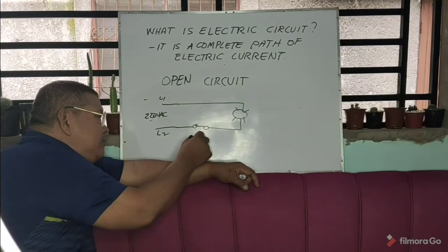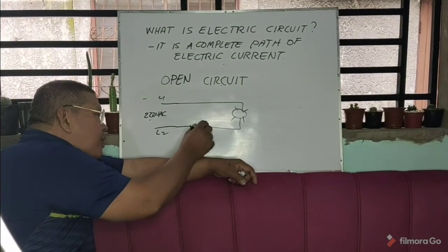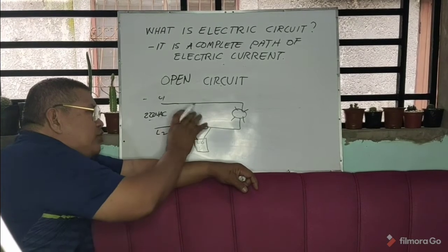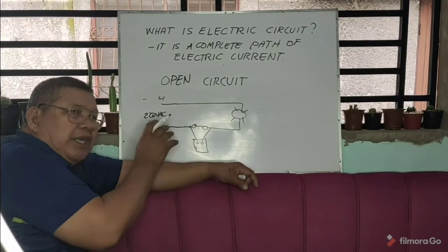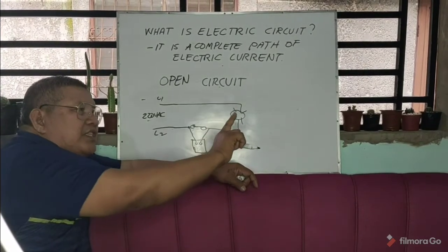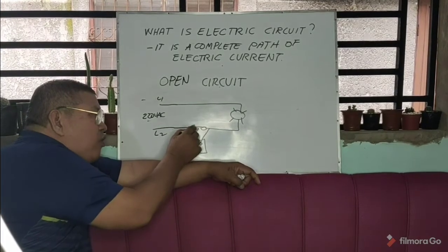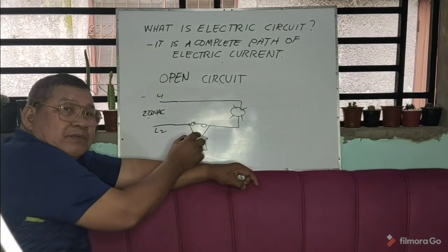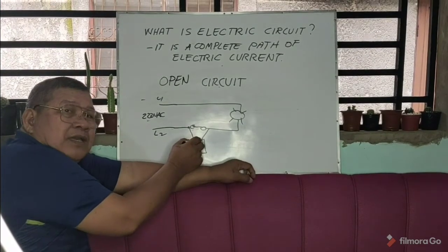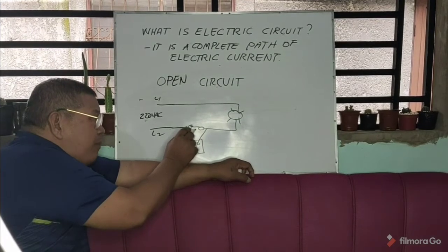That one. You put one rod here, and also put one test rod there, and then switch on and off. If the tester will not move, will not deflect, it means that this is open. The switch is defective. So what will you do? You fix it.